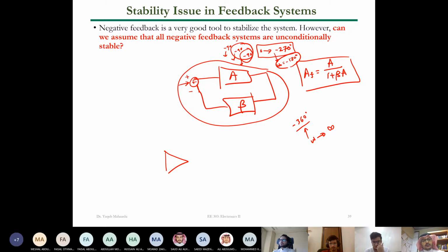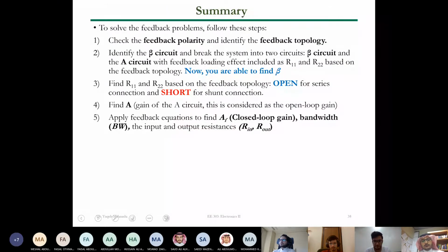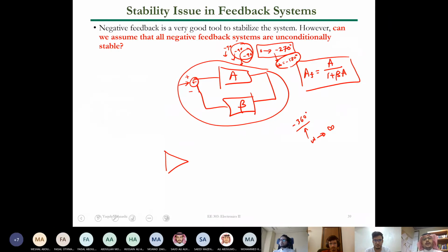So usually in oscillators, what is the oscillator? It is a circuit that gives you an output voltage with almost 0 input voltage. So it is an unstable circuit, and from the name, it is an oscillating circuit. Because we have an unstable system, or a positive feedback, now we can get an oscillator. So the positive feedback, or the instability in the system, is very nice and very good to have if you want to apply oscillators.